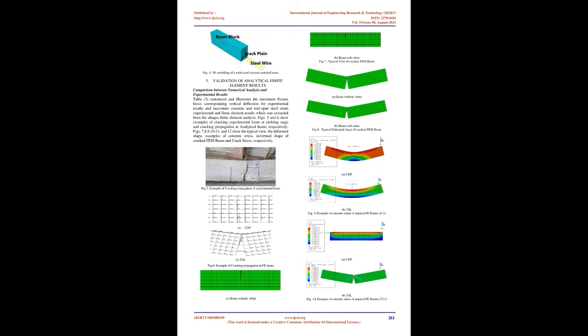A 3-point bending single-edge notched fracture test based on ASTM D5045-14 was used to quantify the fracture parameters. Fig 2 shows the test specimen beam under loading. The mechanical properties of GPC samples determined after 28 days are listed in Table 1.